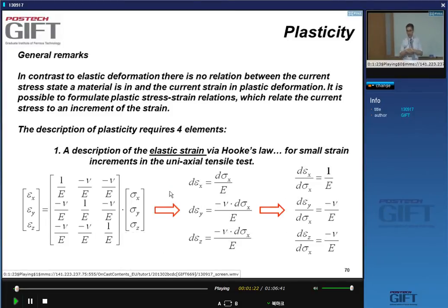All right. So, Hooke's law. We know Hooke's law, the first condition, we already know. We have the theoretical elements to do elasticity. For instance, in the case of uniaxial stress, if I express my Hooke's law in terms of principal stresses, and express this in an incremental way, we find that small increases in the stress result in small increases in the strain, the epsilon.